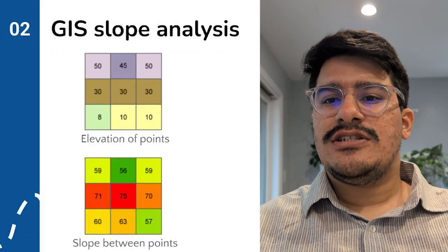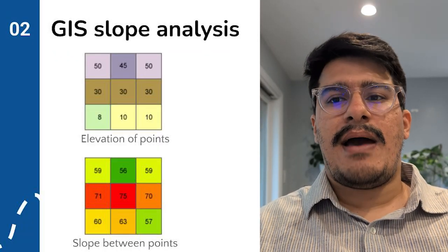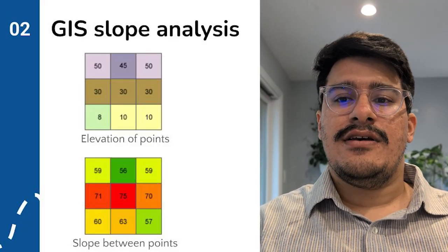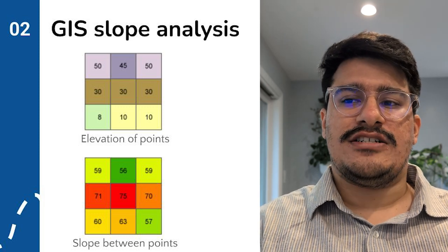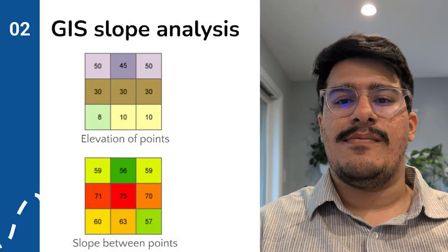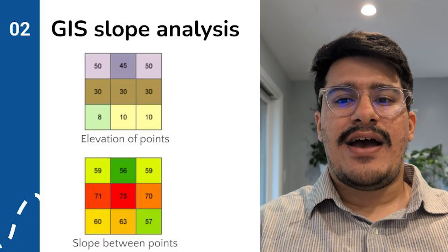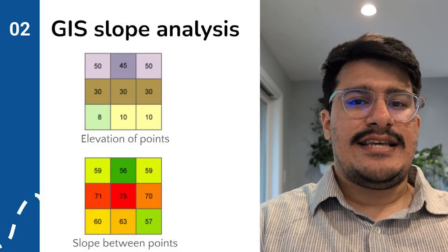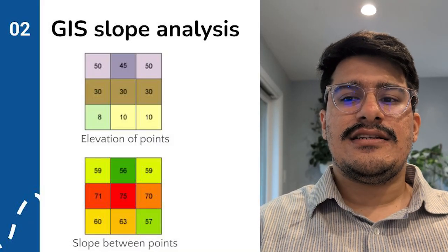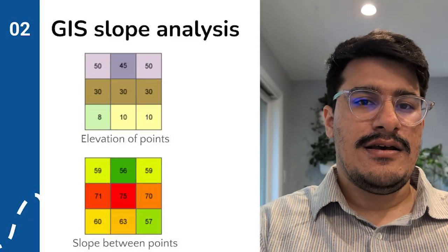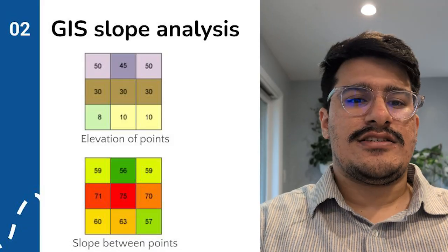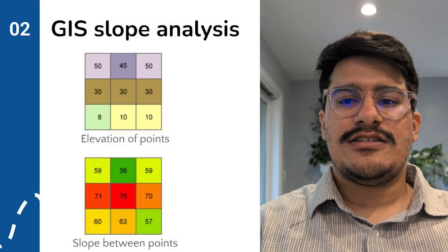Modern GIS have tools that automatically take in a contour map or a DEM, digital elevation model, and compute the slope at every location. ArcGIS has, for example, a slope function. Internally, it uses a model very similar to Wentworth called the planar model. It makes a grid, identifies different points in each grid, and sets an elevation of those points. Look at the box on top. It then calculates the steepest rate of change in elevation from that point in the grid to a point in the next grid. Technically, the tool fits a small plane or a surface and finds the slope of that plane.